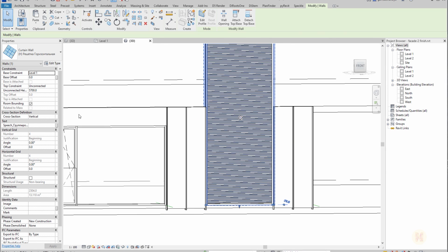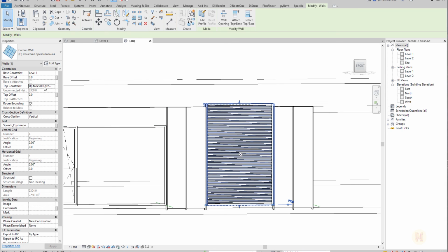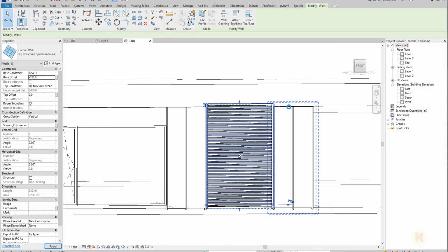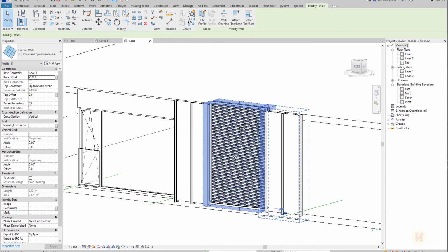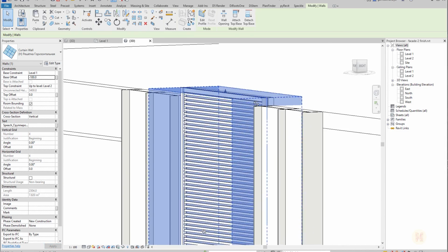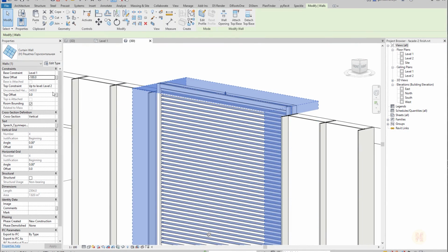The second thing we should do is that it's not right with the size. Again, we already talked about going to the second level. I will do this till the second level. Let me wait, because it takes time again, as I said. And for the top constraint, we use -100. So now it will fit perfectly. Let me wait. No, it doesn't fit perfectly. Why? It doesn't fit perfectly, but we did everything right. Okay. Oh, top constraint, top offset.